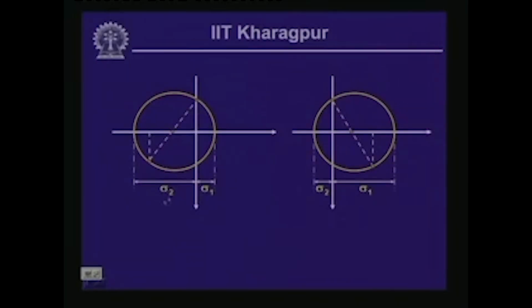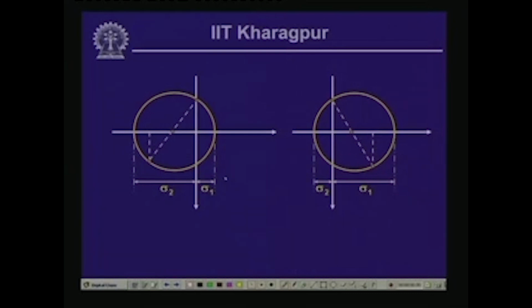As you can see from practical examples, a beam member is subjected to axial pull and transverse load because of some loading situations, where we compute the normal stress and the shearing stress individually and then combine them together using the Mohr circle to find the resulting maximum or minimum normal stresses and the maximum value of the shearing stresses. This is what is shown here: if you get the normal and shearing stresses, you can plot them in the Mohr circle.